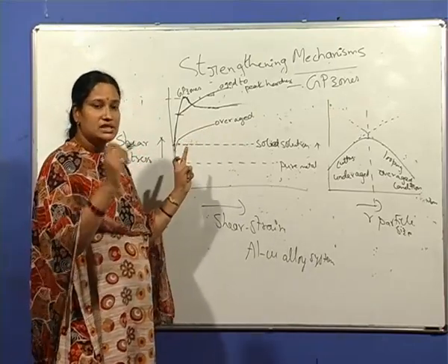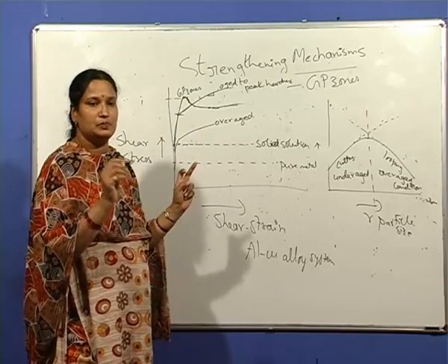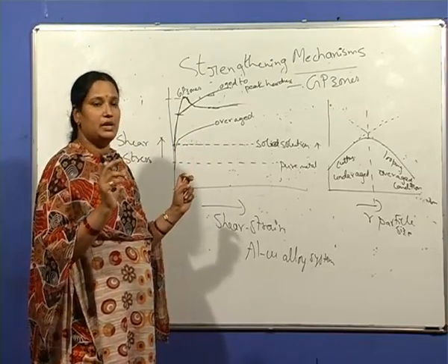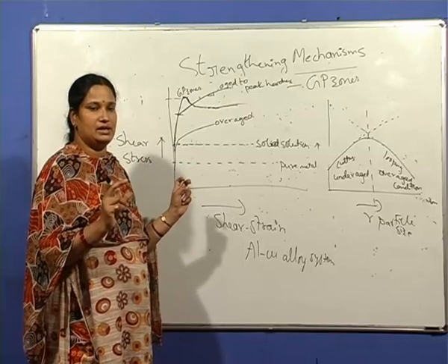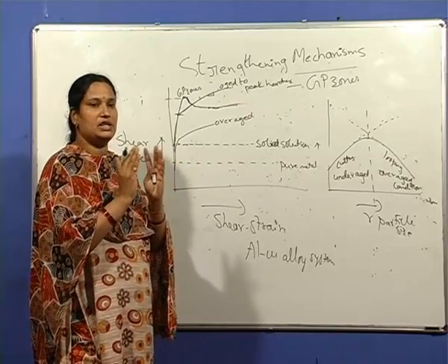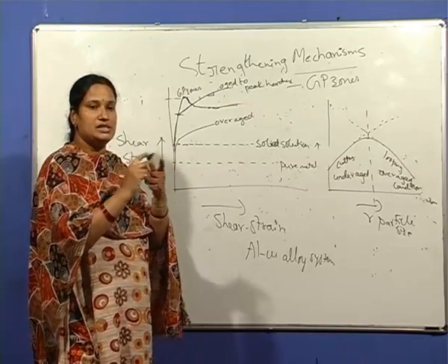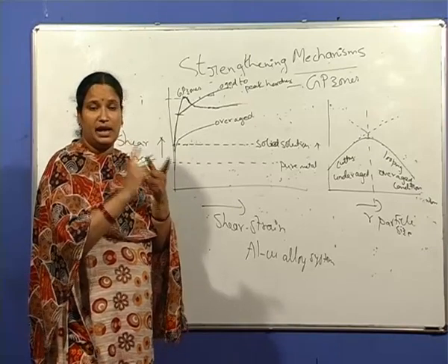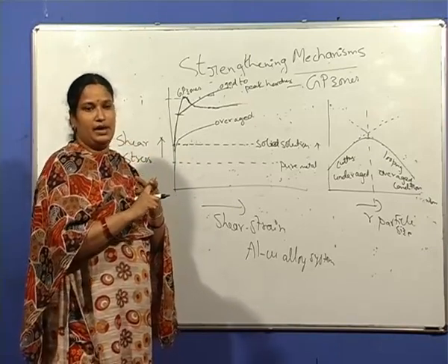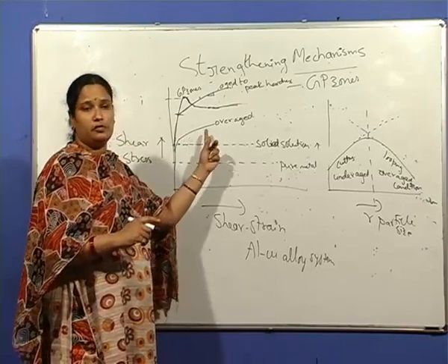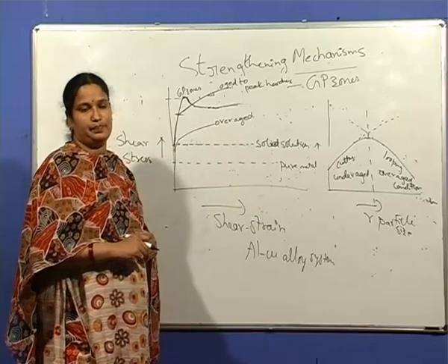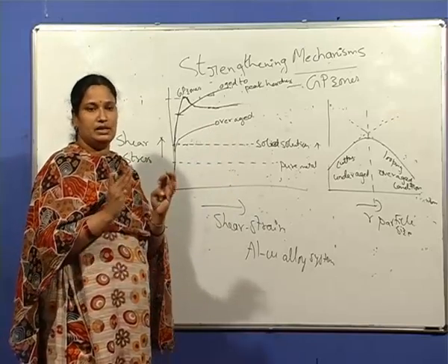but the dislocations form loops around the precipitate particles, the coarser precipitate particles. Because of these loops that are formed, the dislocations form tangles, and the rate of strain hardening is higher because of the formation of these tangles.